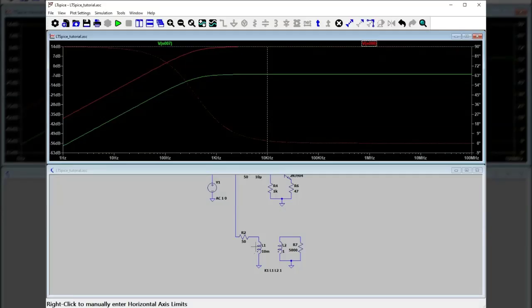Well, the current has to enter the positive terminal of a load. That's one of the fundamental assumptions in our circuit theory. And then the source, however, the current exits the positive terminal of a source. And this secondary of the transformer is a source as far as this resistor is concerned. So current would be exiting the positive terminal of the secondary when it's entering the positive terminal of the primary. And that's the reason why we have this rule with the dots.